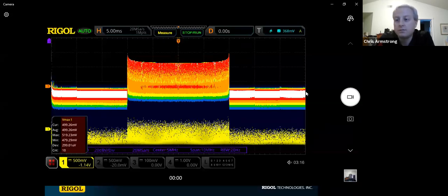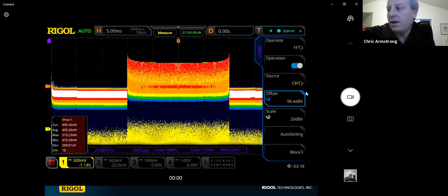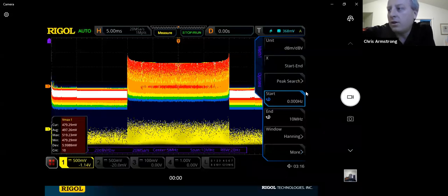Here I've done a color-graded FFT over top of the primary signal to show that precise modulation. We're seeing it in the 0 to 10 megahertz span here. This is a 70 meg scope, but just a little modulation signal I put in there on the FFT.